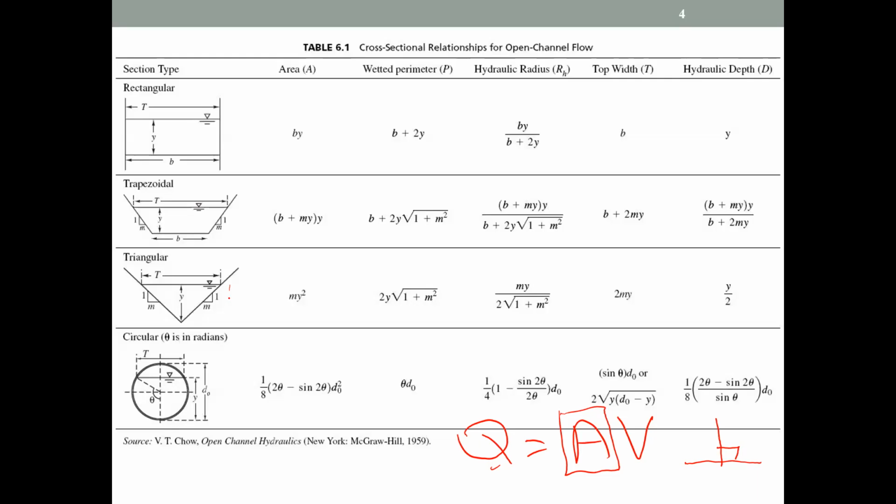So what happened in that time? You see, this part of the channel is filled with air. In other words, it is open to the air. That is why we call it the open channel flow. All right. But you understand, on all these cases, the free surface is open to the atmosphere. Now, we need to understand what are these parameters that we will use in the equations. Like, for example, the area. It is very simple to understand. If you use a rectangular cross section, area is simply B multiplied by the water level height, right?